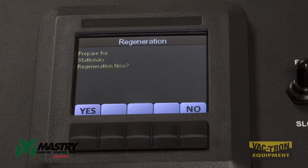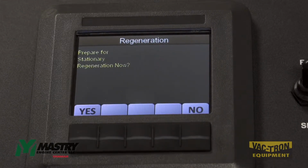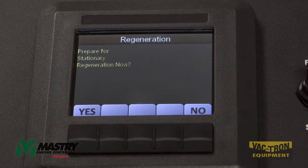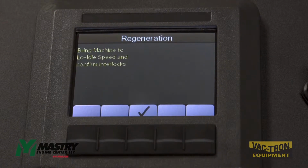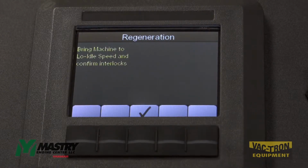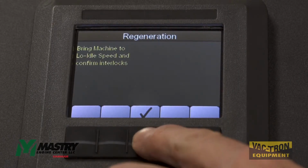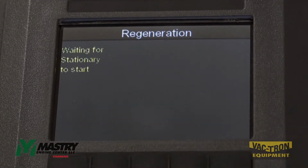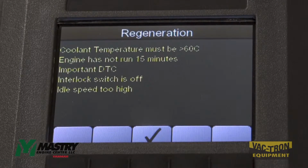In order to prepare for stationary regen, certain conditions need to be met, one of which is that the speed needs to be set to the slow speed and not the high speed. If this is not done, then when you hit yes, the panel will ask you to bring the machine to low idle speed and confirm the interlocks. At this point, if you're still at a high speed, it will ask you once again if you're ready. It will wait for the stationary to start, and then this error message will pop up.